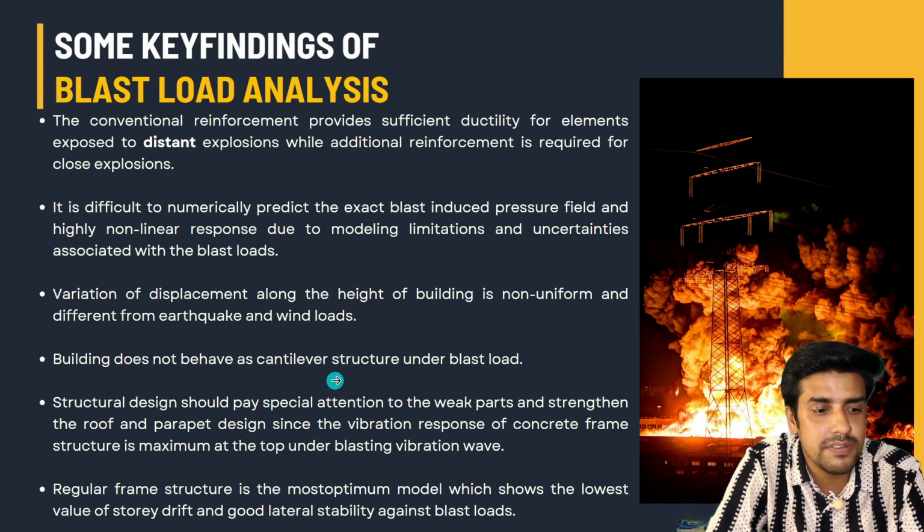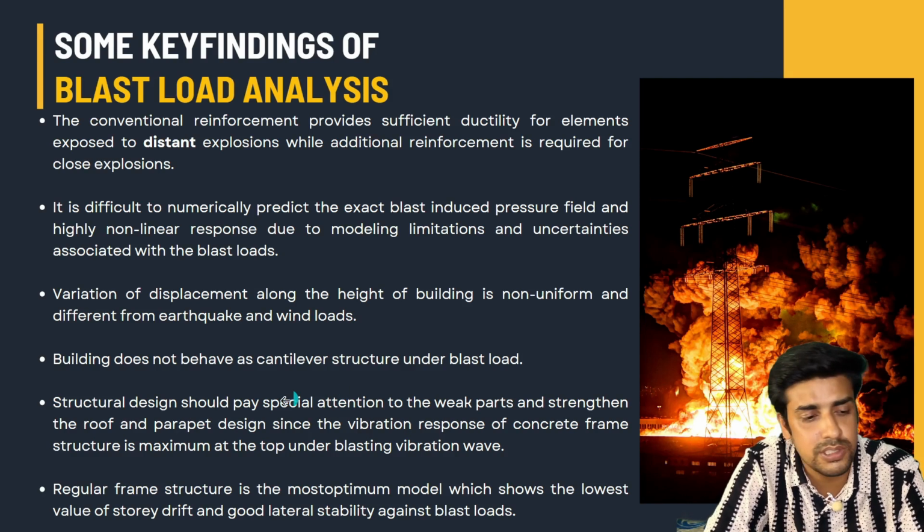A building does not behave as a cantilever structure under blast load. That's the very major thing. If the blast or impact happens at the midpoint, then the building is going to behave in a totally different way. It is not going to behave like a cantilever. The response will be maximum at the center and minimum at the bottom and the top. So it will be totally different. A non-linear, or not uniform, response is going to be there.